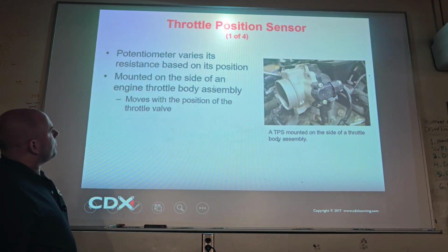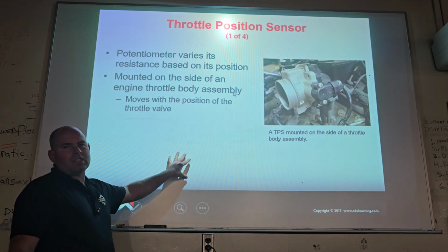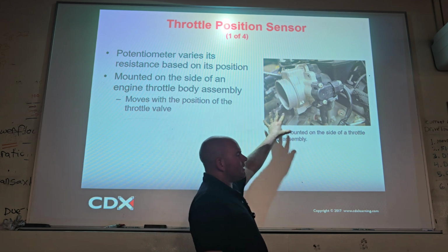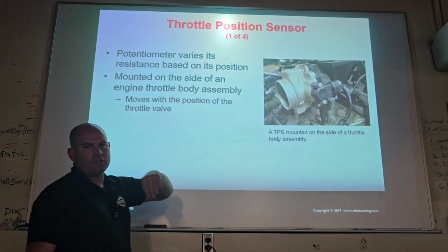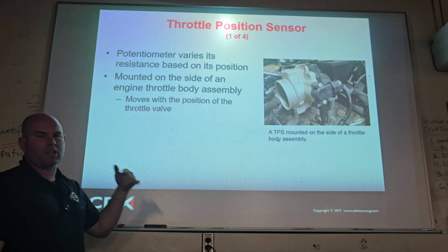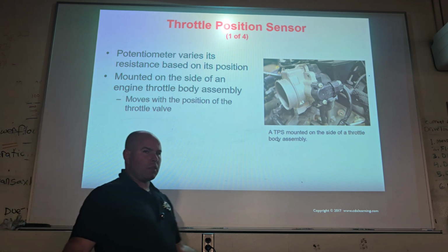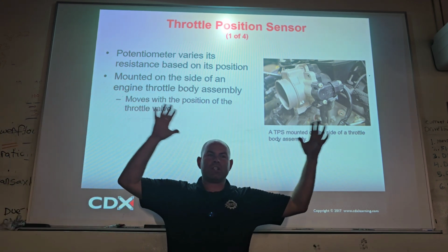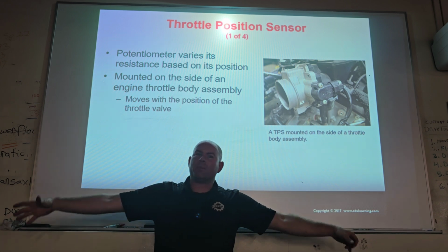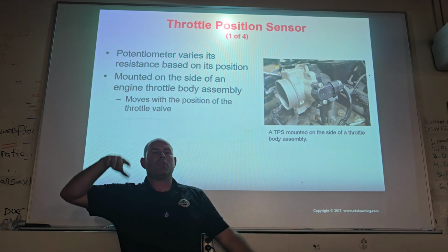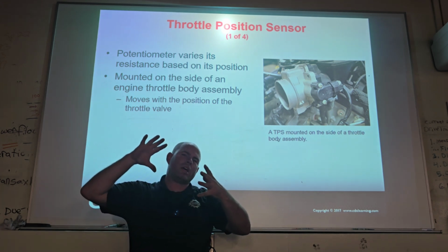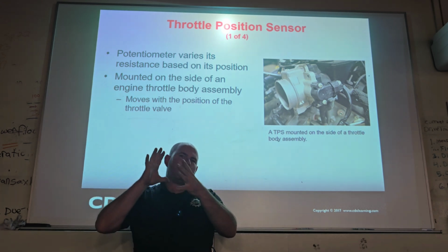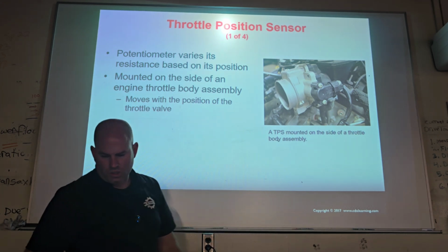Okay, now talking about throttle position. Diagnosis is the same. The reason you'd like to know is because the throttle position is an input to the transmission when it generates line pressure, when it controls shift timing. Remember, we had the throttle pressure and the governor pressure, right? But those are gone. We replaced the throttle pressure with the throttle position sensor voltage, which we put into a table, and we use logic to determine when the shift would be.